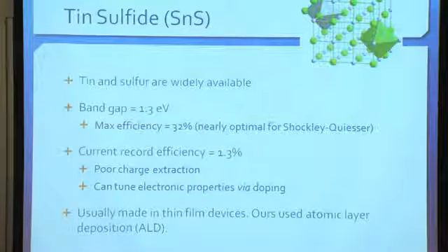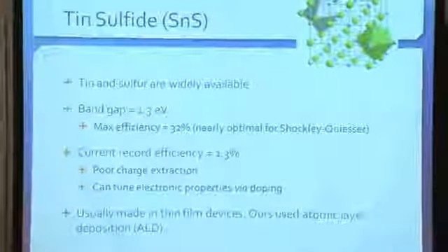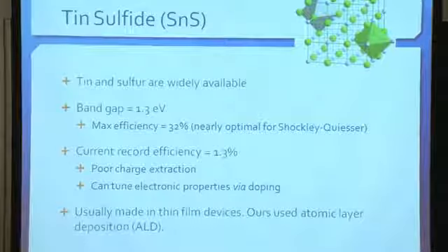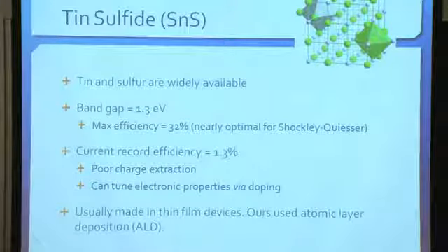Often it seems that devices are limited by their charge extraction. There is an interface between the absorber layer and buffer layers that block electron and hole transport. I'm going to talk about that a little more on the next slide. But this interface has been, unfortunately, not very well characterized to date and is often a site of high recombination rates that can limit the current extracted.